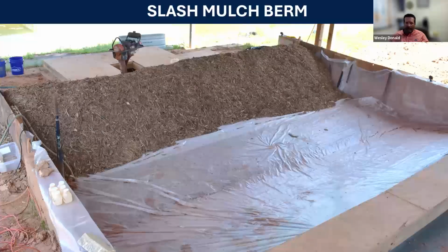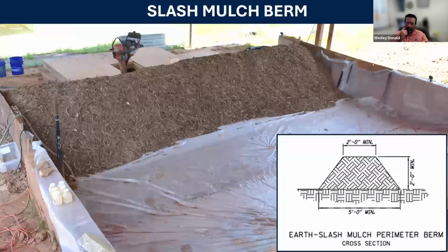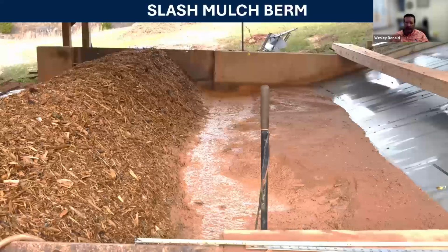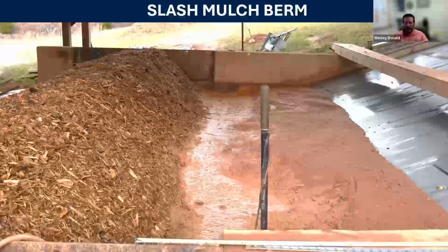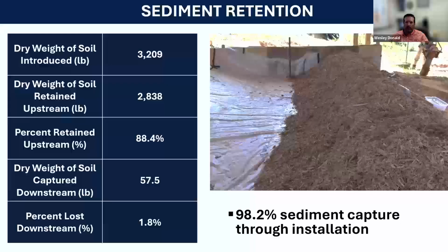And we abutted it to the downstream side so that it discharges directly into our downstream containment system. What we found is, yes, we get sediment capture upstream, but look at the impoundment. You can see the mud is barely built up, maybe less than a foot on the upstream side. So we're obviously not detaining it for a long period of time.